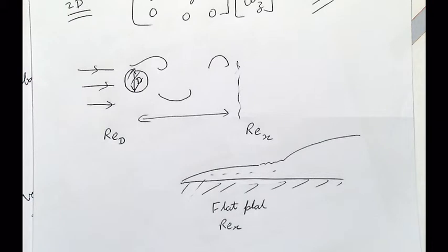I have to tell you about wave numbers. At low Reynolds numbers, there's not an opportunity for these larger scales to keep breaking down into smaller scales until viscous dissipation happens. At low Reynolds numbers, this viscous dissipation happens very close to where these large scales are being formed. So there's no need to establish this cascade of energy. That's why for low Reynolds numbers, we can use 2D simulations, and maybe even 2D experiments.